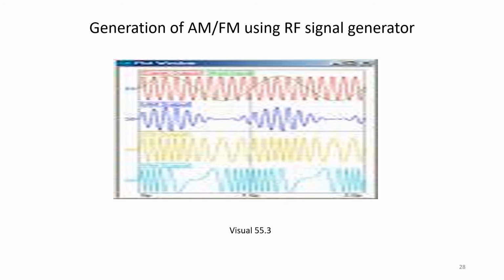Generally, these RF signal generators are used for troubleshooting in our radio and TV receivers. So these RF signal generators are used for adjusting of amplifier frequency response, the testing of amplifier frequency response, troubleshooting and repairing electronic devices, checking and testing the lab equipment, generation of AM, FM modulated waves for testing the communication receivers, measurement of gain of each stage at RF frequency, and can be used to determine the distortion characteristics of an amplifier.